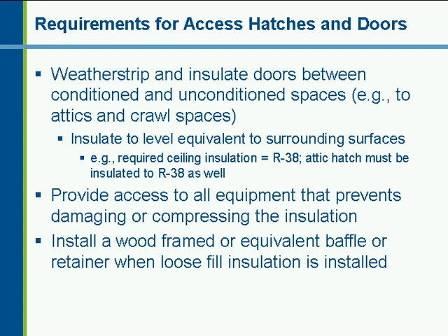Finally, there are some requirements related to access hatches into the attic. This actually applies to access hatches and doors between any conditioned and unconditioned spaces, but for the most part, this is doors and hatches into the attic or perhaps into a crawl space. There's a requirement to insulate those doors, and in particular, you have to insulate it to the same level as the surrounding element that it's in. So if you have an access hatch into an attic with R38, the access hatch itself has to be insulated to R38 with appropriate provisions to, for example, a baffle or a wall retainer to hold loose fill insulation away from that opening when it's opened.